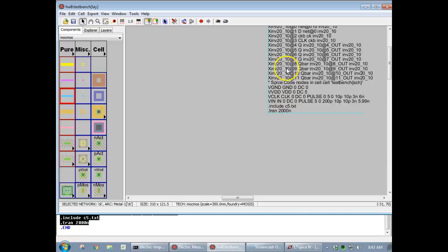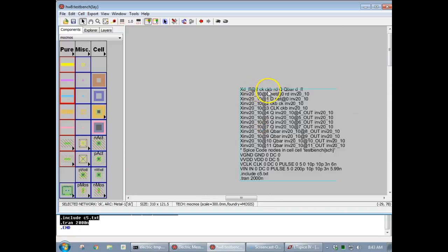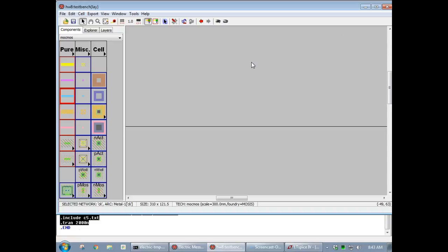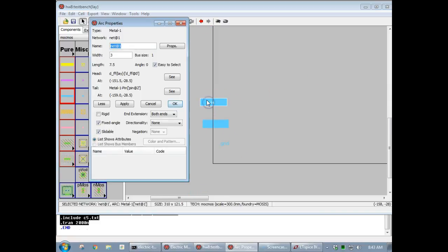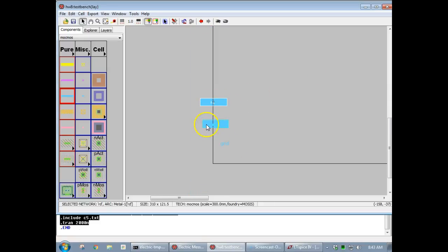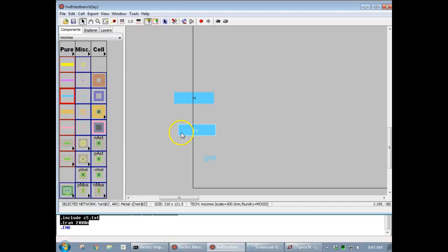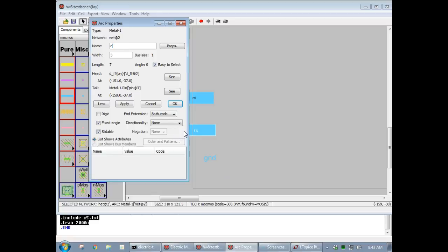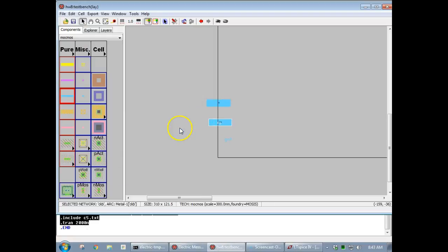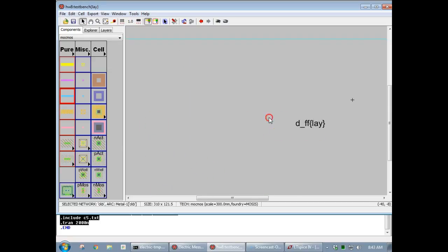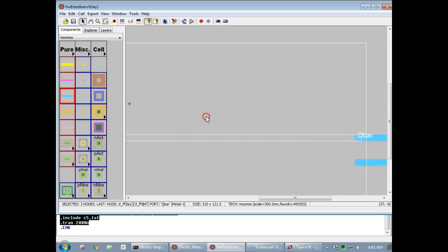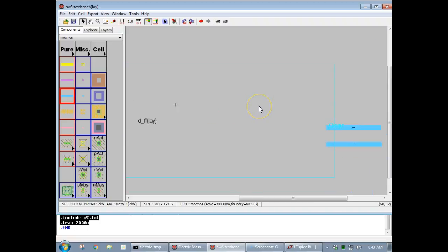If you remember, that's what the clock was called, that node, CK. CKB, wasn't me that named it, it was actually Aaron. That's RD. This one is going to be called, I forget, what's that hooked to? Clock bar. CKB. Is that all our pins? CK, CKB, D input, Q and Q bar. And don't draw that wire.